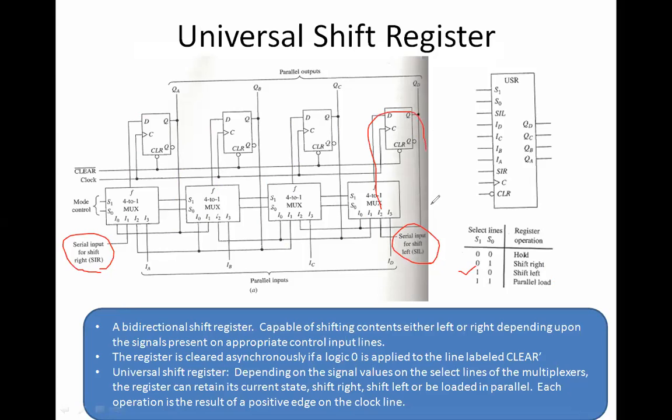And this gets connected to I2, right? I2 gets here, gets into the third flip-flop, comes out, and then it gets in here, right? The same thing comes here to the second flip-flop and comes down, and then now it is entering into the first flip-flop. So I2 is selected, the output comes, and finally you will have your bit, which is QA. So from here it is shifting. Is that clear, all of you?